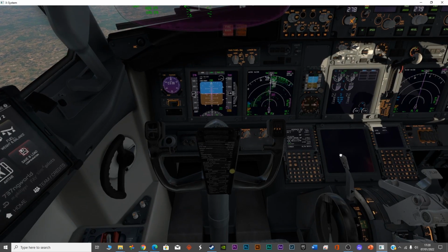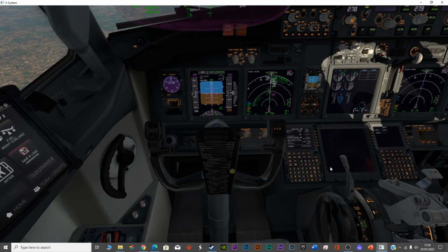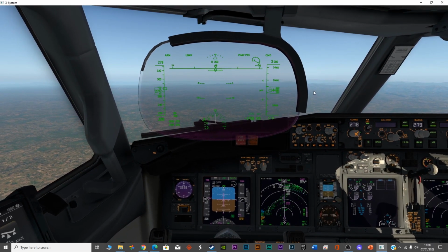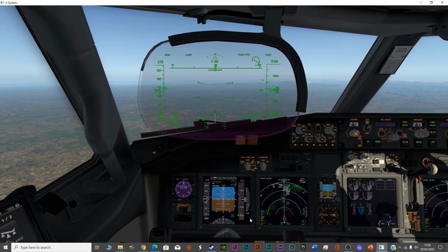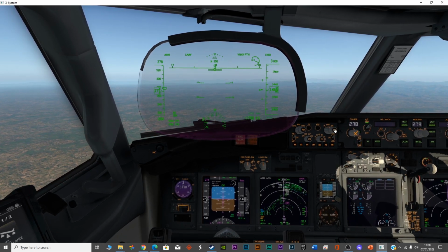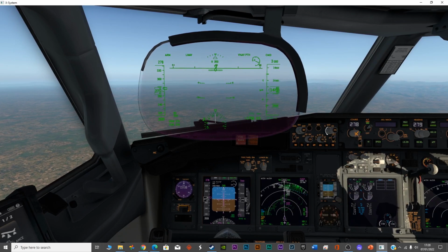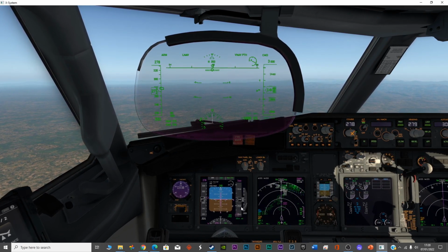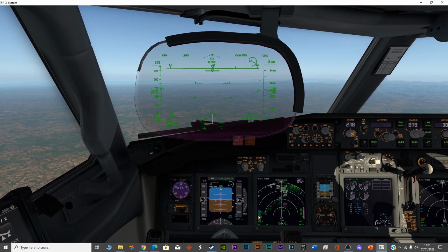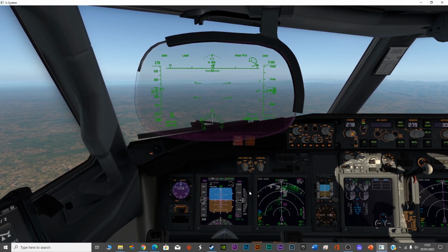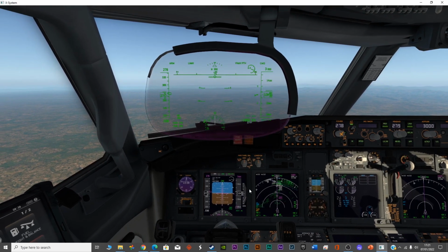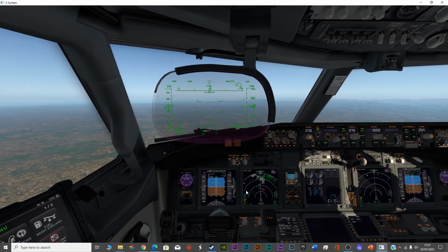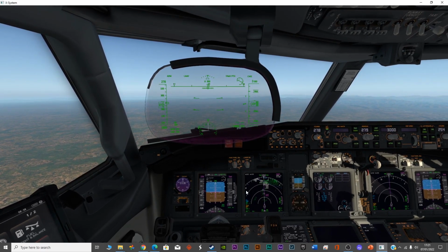Okay, so it is armed, and let's see. I don't think so. So you can see now standard has turned into this mustard color. I will change it to QNH and 1014. That's it. So now the altimeter is set. So you have to set the barometric pressure over here so that the altimeter gives you the right readings. Otherwise, some miscalculation can result in a disaster.